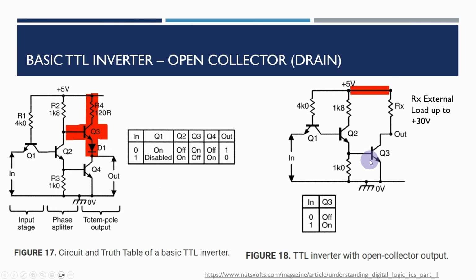So when you've got an open collector one, it basically means that you may need a pull-up resistor if you want to actually see a 1 voltage coming out. What it does mean is that we can connect it to different circuits, and this is also sometimes used where we want to have a signal, perhaps like a reset or an interrupt. We could have multiple outputs from multiple chips all connected together with a single pull-up resistor, and they wouldn't cause a problem.